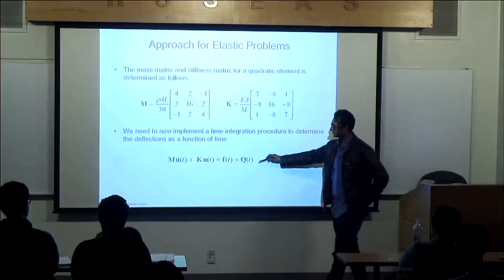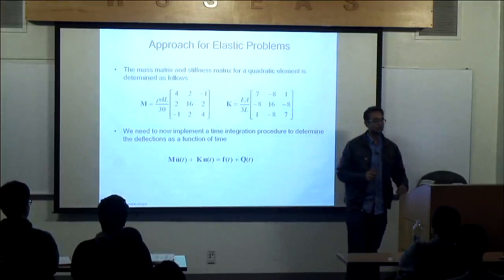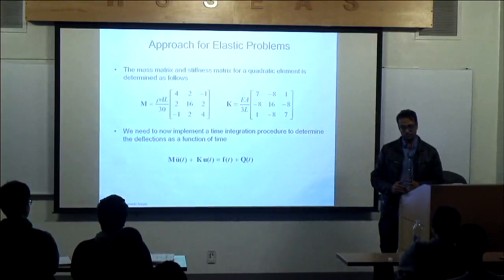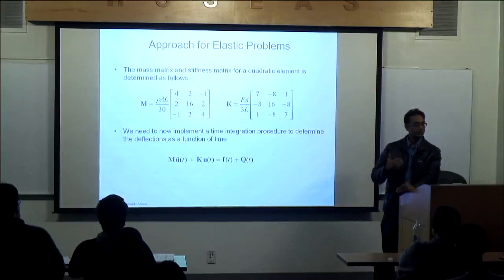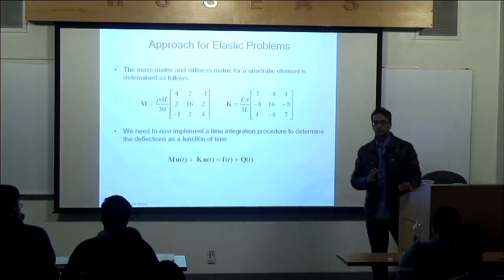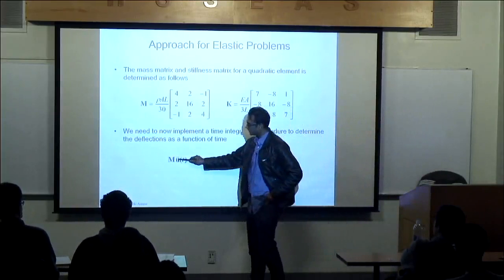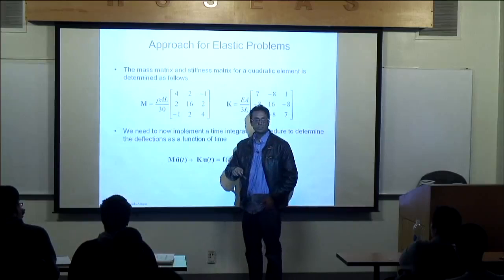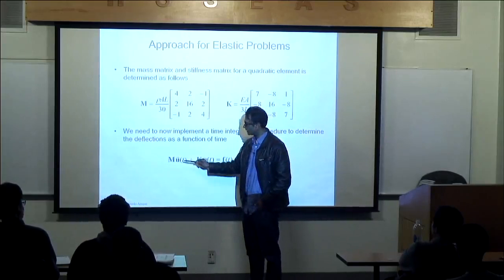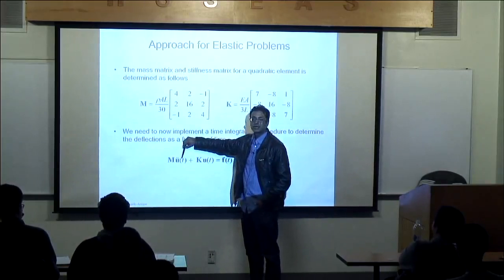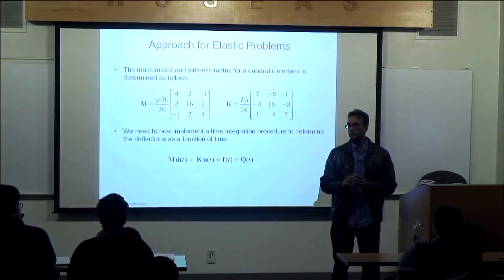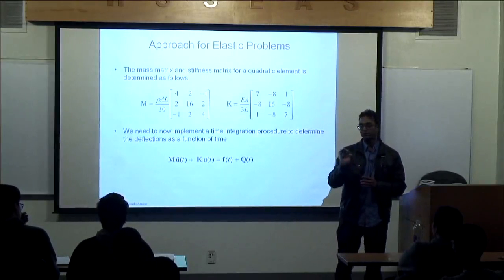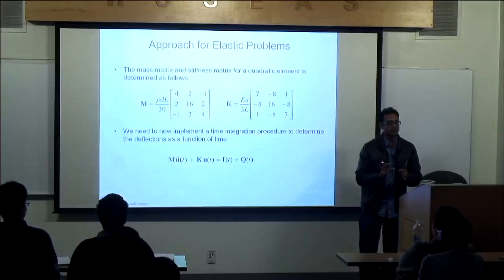So, how do I solve this? How do I solve this? Okay? So, I'm going to try to cut to the chase. Normally you'll teach Euler. Remember last week we covered backward difference, forward difference, central difference, right? That works very well, actually, for problems where the derivative is with respect to time, only one time derivative. If you remember, heat transfer and moisture diffusion problems have only one time derivative. This has an acceleration term now. So I'm going to cut to the chase and get as close as possible to what Abaqus has in their code without getting into the minutia. You understand what I'm saying? So I'm going to cover the method that's the closest to what Abaqus has. Okay?